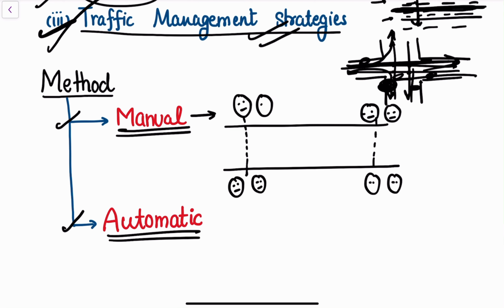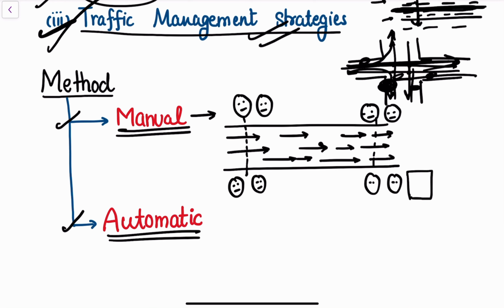Now this group of surveyors records the vehicles that are moving in the study section for a certain amount of time. That is, if you are going for a 1 hour traffic study, they record the quantity of traffic moving in the study section for 1 hour. Likewise, they can do it for 24 hours. Likewise, the study can extend up to 1 full year. So these surveyors have a data log where they record the vehicles, and the type of vehicles, passing in the study section, and at the end of the day, they match their data log.